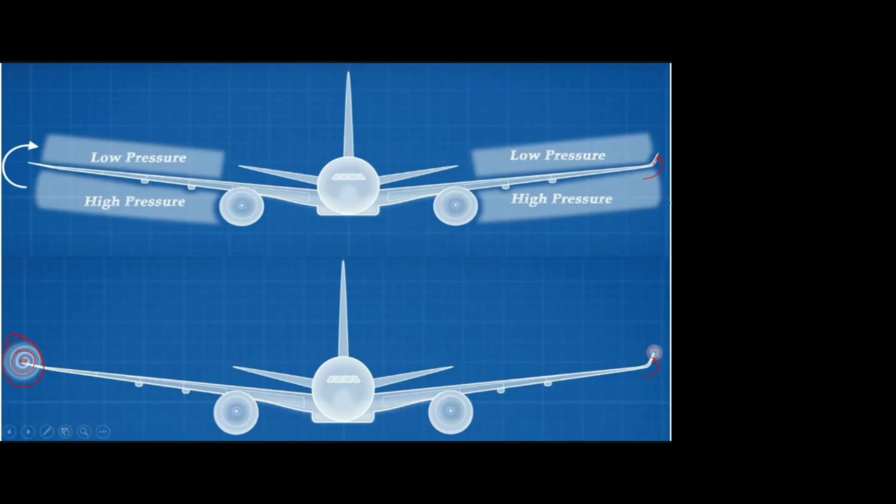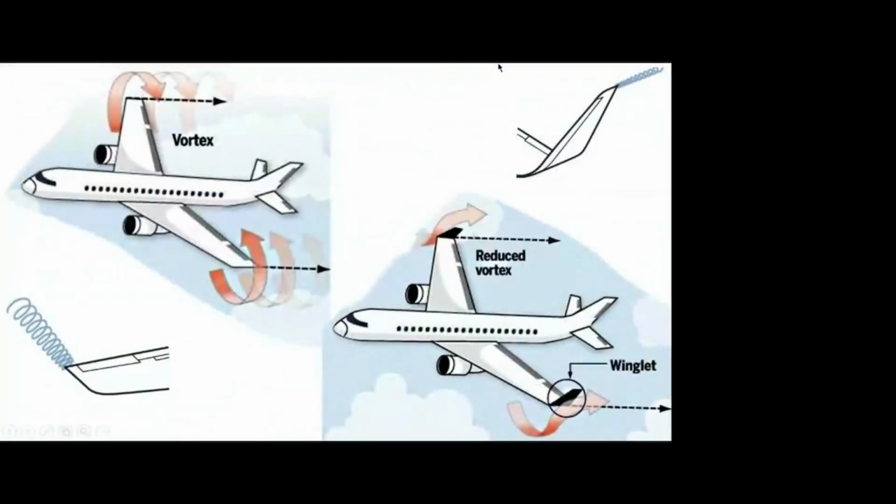So using the winglet, we can stop the side leakage flow. Again, there will be a small wingtip vortex from the tip, but the strength is very small compared to this wingtip vortex. So the induced drag also reduces. And here they explain, yeah.